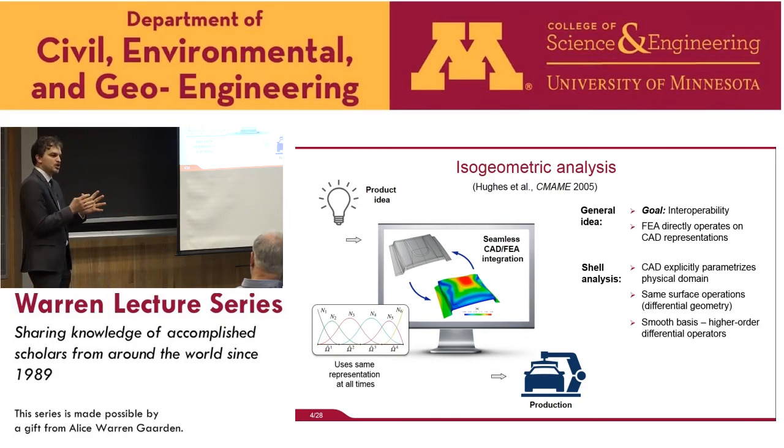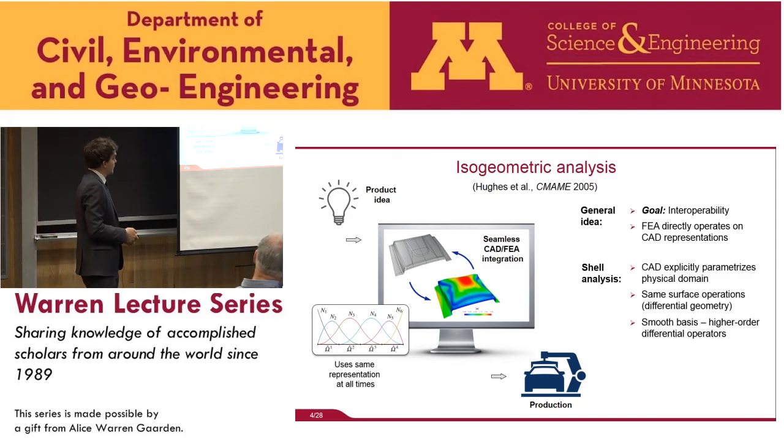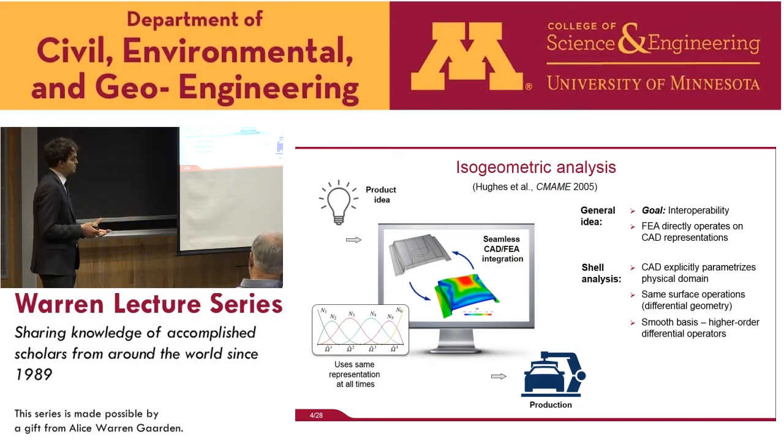If you think in terms of 3D structures, they're often given in terms of boundary representations, where you have a surface parameterization, but not a volume parameterization. Then in the case of shell analysis, the CAD model and shell finite elements are based on the same surface operation based on differential geometry. And the third point is that the smooth basis functions are ideally suited for discretizing higher order differential operators as they arise in thin shell theory.